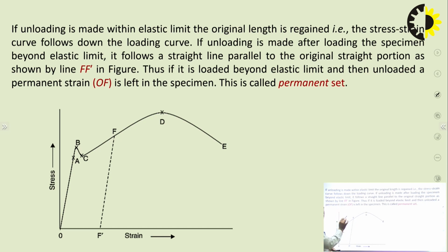But if the specimen is stressed beyond the elastic limit and unloading is performed, then the unloading curve will be a parallel line, parallel to the elastic-limit portion of the stress strain curve.